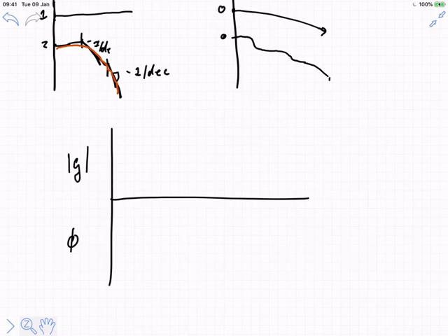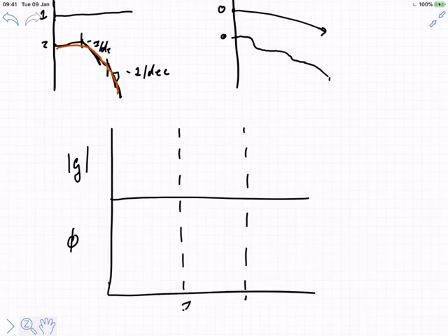So we've got the gain part, and we draw in these two. Now again, I'm drawing this not to scale, right? 1 over 3 and 1 over 2 aren't necessarily exactly where I've drawn them over here, but they are in this order of that gain part, and this eventual slope here will be -2 per decade.